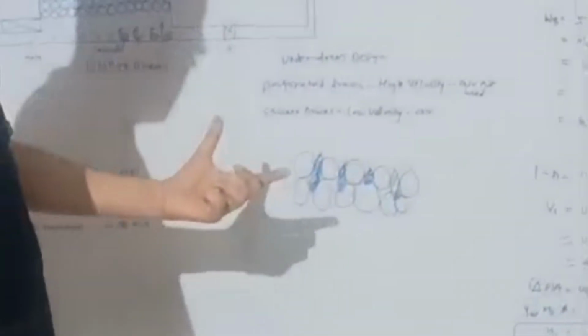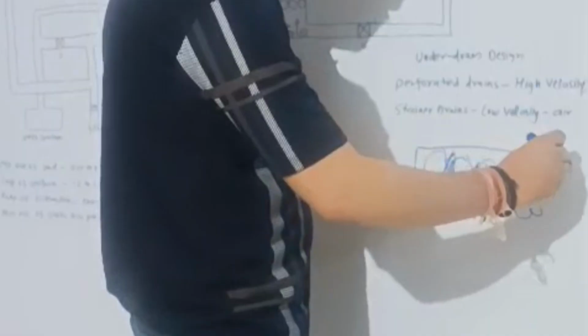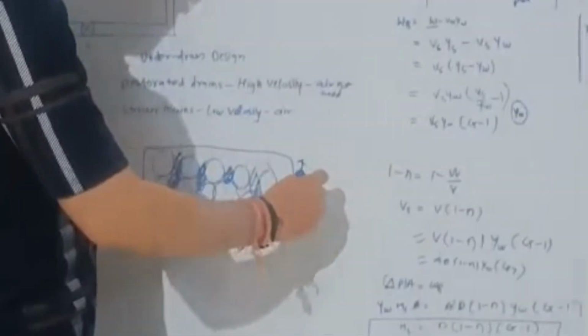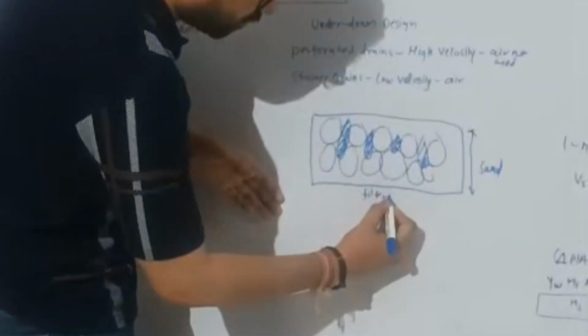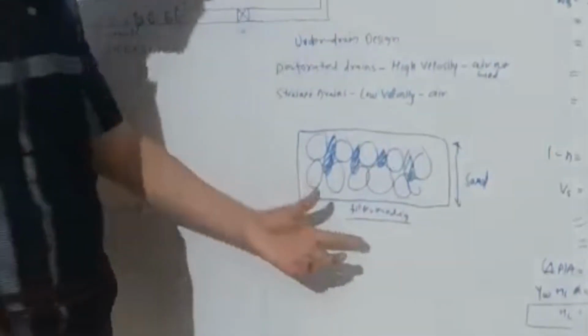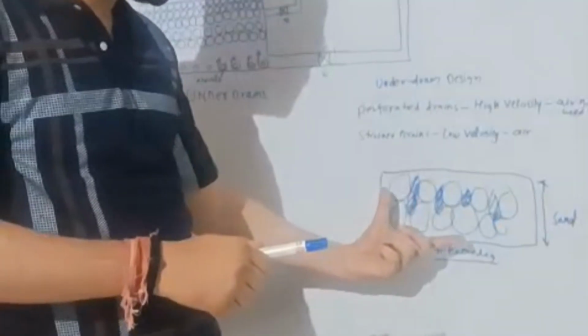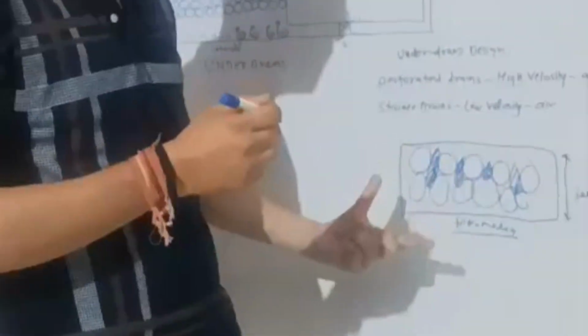When some types of impurities get lodged in the bed of the filter media, which is the sand we have provided as the filter media in the rapid sand gravity filter, and we perform backwashing, the bed is expanded and has more voids. The size of the voids is more than the previous voids.